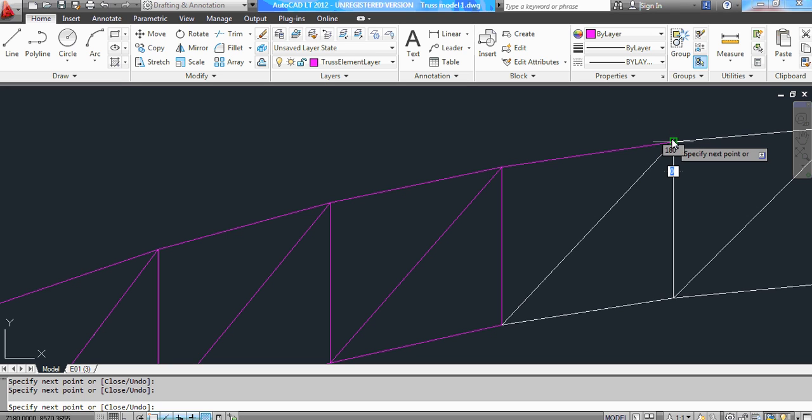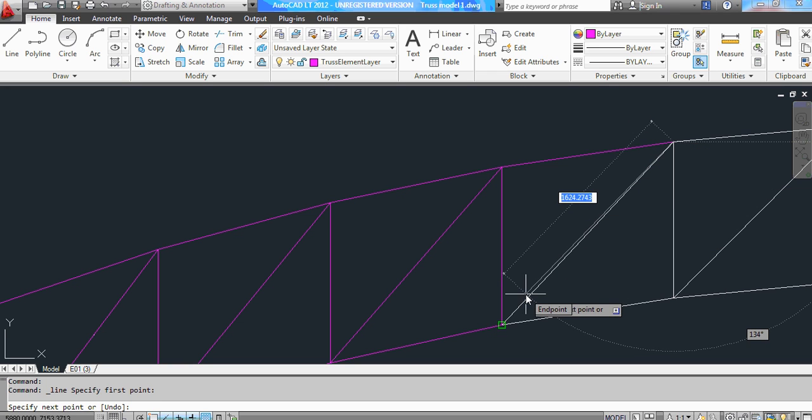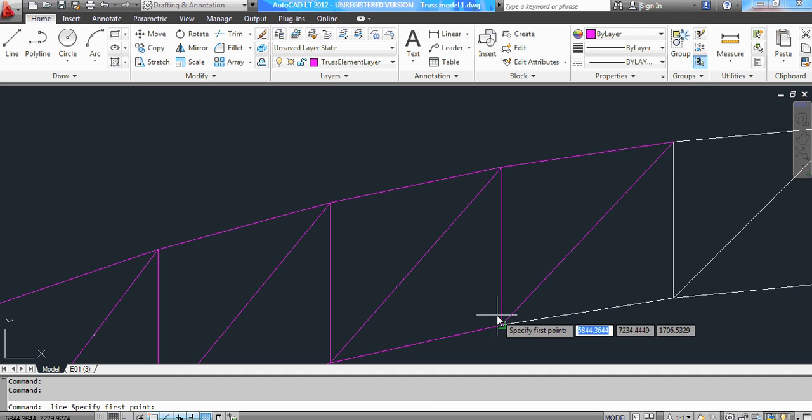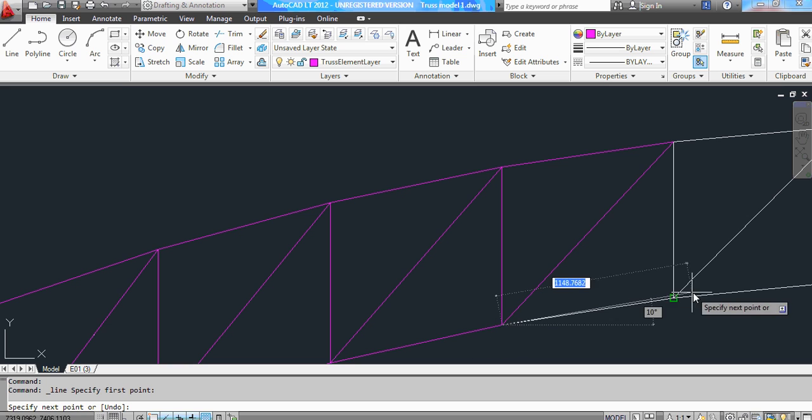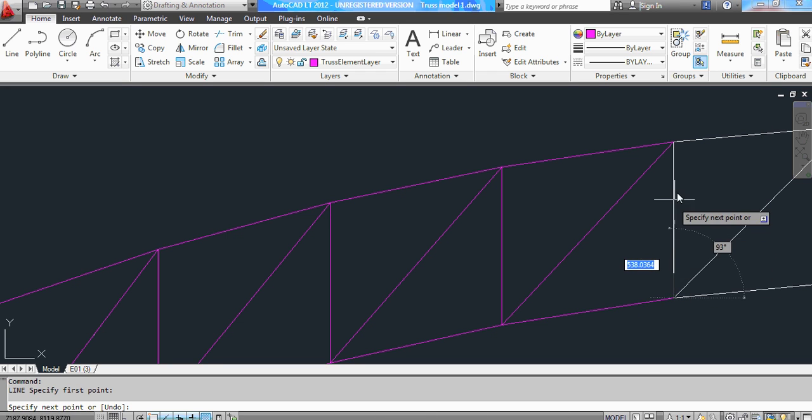Take the lines one after the other, for instance like what I have now, and then I'll come back and draw this. Okay, go again, click on this, click, or you can right click to repeat the last command. Depending on your settings, you can right click and the menu will not come out, and then you just click.